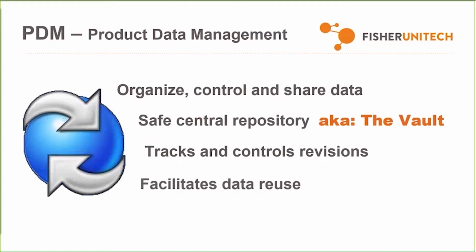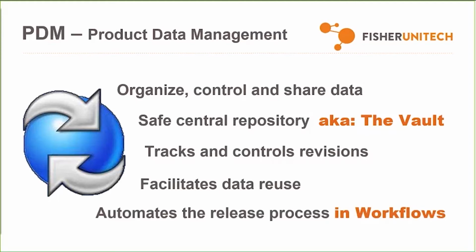It facilitates data reuse. If you want to use a component from another project, you can add it to your design, you can rename it, you can move it to a different folder, and you will not compromise that other project. PDM retains all those complicated file relationships. A workflow is set up in PDM. This is the development cycle specific to your company's procedures, and it automates the document approval process.